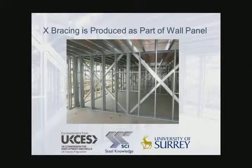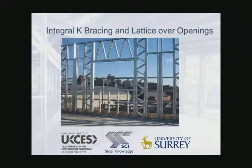Here we see a good example of X-bracing produced as part of a wall panel. In this case, it is a double leaf wall that's used for a separating function between two apartments, and as you can see, the bracing is contained in the space between the C-sections. Integral K-bracing is often used around openings and lattices over openings, particularly large windows, and we can also see here the use of double C-sections above and below the windows and triple C-sections to either side.